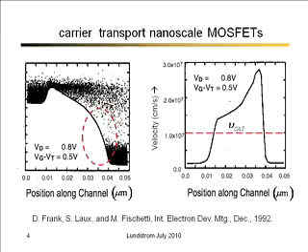So if you look at the drain in this simulation, the electric field is very, very high near the drain end. But if you look at the average velocity, you can see that it's very much higher than that saturated velocity of 1 × 10⁷. And that's just a reflection of what can happen in a very short device where there isn't time for the scattering really to come to steady state and to equilibrium. The electrons are out the drain before they've had a chance to scatter enough for their velocity to saturate. So this is called off-equilibrium transport. Things get very complicated in these small devices.